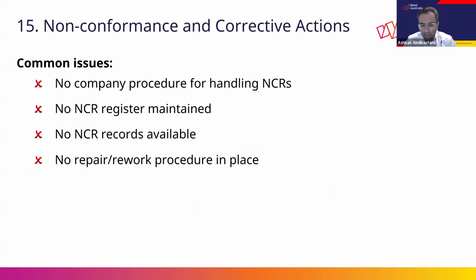Because if you have an NCR and the corrective action needs a repair, you need to have a procedure in place. Sometimes the WPS you have for production doesn't cover the repair welding. That's why when you have a repair or rework, you need to make sure you have a procedure for that specific repair. And if any specific WPS is required, for example, if you have a buildup due to excavation of the defect, you need to develop that procedure and WPS to make sure it works properly.